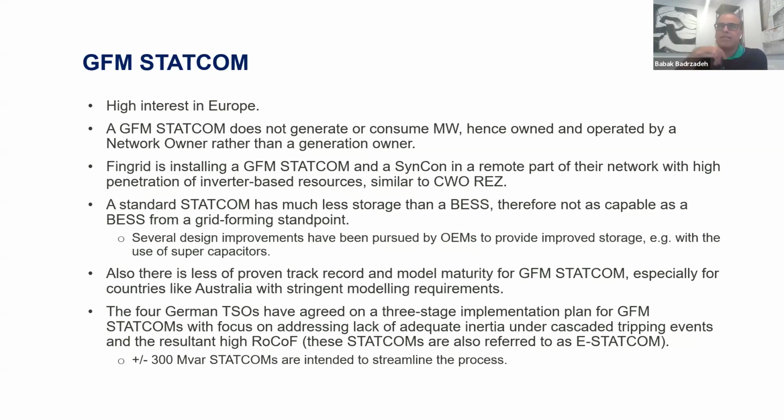So if you were to have a back-to-back technology, then if your shore side is grid forming, the offshore side must be grid following. At the same time, the offshore side is a dead network until it is established. And that's why it would be desirable to have wind turbines with grid forming capability, but that's more demanding. So it is possible, but it's not as easy as battery storage systems. Now, one other difference between HVDC and battery is that there is not really a significant capacitance or energy storage that you will have in the battery.